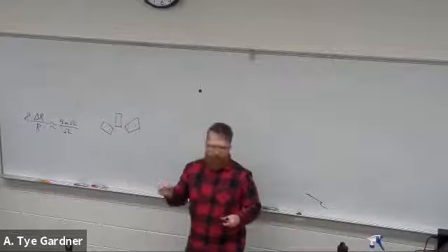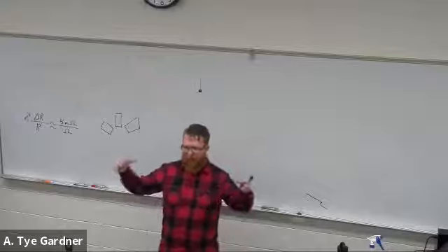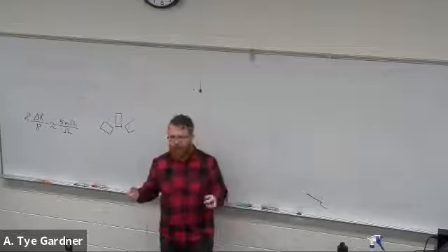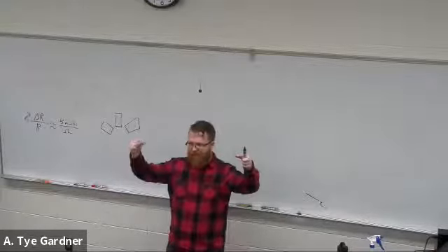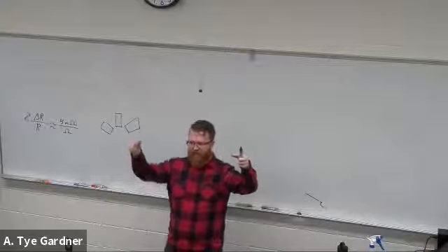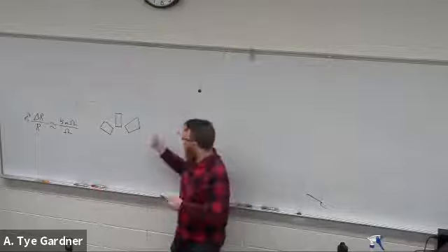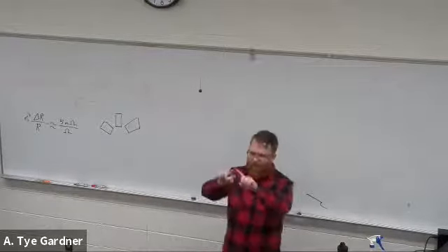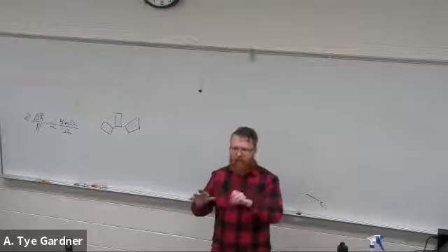The other way that we deal with this error is, notice how it's really long in one dimension and not the other. That is a nice mechanical way of dealing with these errors, because it's very hard to torque in this direction and very easy to go this direction. So therefore, we have a mechanical method of ensuring that we don't get directional strain. And you'll see full 180-degree versions that will measure the strain in any direction.